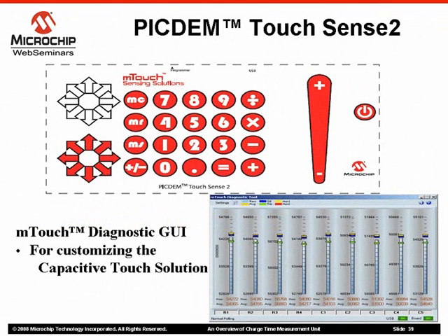As I mentioned in the earlier slide, the PICDEM TouchSense 2 demo board DM164128 demonstrates CTMU in capacitive touch sensing application. This board has implementation of direct keys, matrix keys, and linear slider. Also, this comes with a free graphic user interface for diagnostic and customization purpose. Using this graphic user interface, you can customize your own capacitive touch sense application. Please refer to the documentation by visiting www.microchip.com/mtouch.